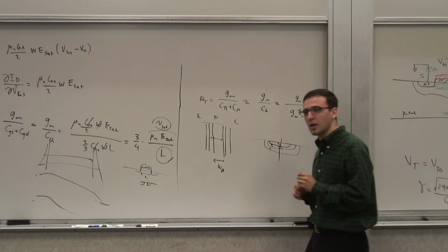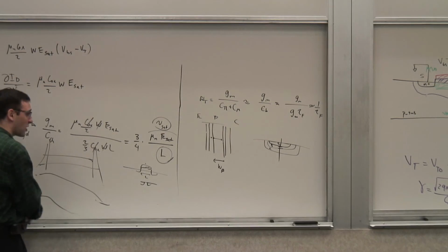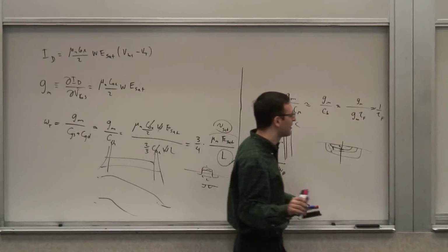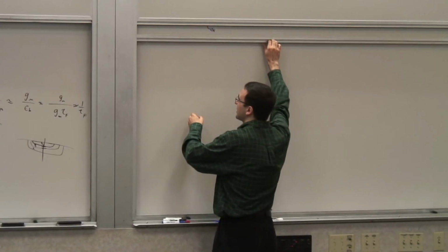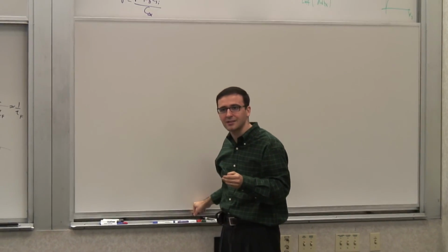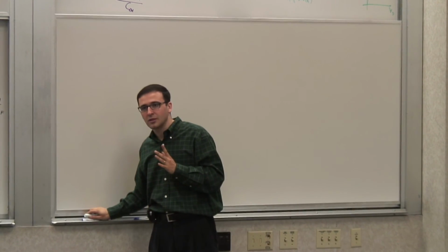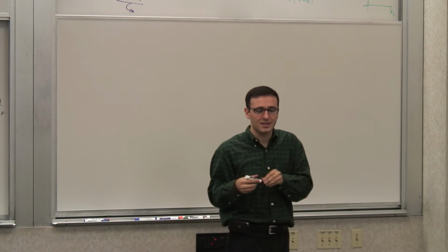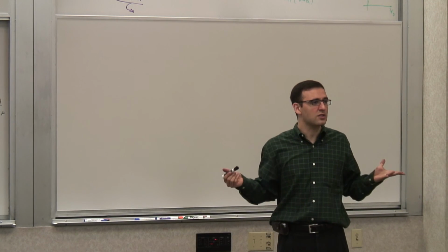Now there's one more thing I would like to talk about before we go, and that's the subthreshold. That's the last topic on the device physics. It's kind of a short topic, but I just want to make sure that we talk about it. Now, remember, in everything we said so far, we assume that the transistor is off below strong inversion, right? But we know it's not off.